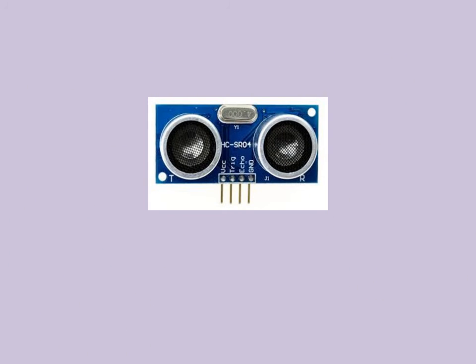We chose the ultrasonic sensor to detect an intrusion within our system. This device allows one to calculate the distance of an object in front of it, which bounces ultrasonic pulses to and from the sensor. Through continuous polling, our microcontroller will be able to detect a change in distance when an intruder crosses its line of sight.